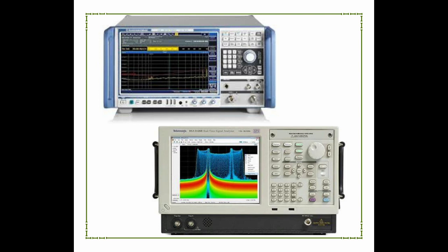And here are some major differences. EMI receivers typically focus on a narrow range of frequencies, usually 9 kHz to 30 MHz. Emissions measured in the frequency range of 30 MHz to 1 GHz with a resolution bandwidth of 120 kHz are displayed as a field amplitude in dB microvolt per meter versus frequency. Spectrum analyzers, on the other hand, are generally less sensitive but offer more detailed information about the frequency and power of signals. EMI receivers are typically more sensitive than spectrum analyzers as they are designed to detect very low electromagnetic interference.